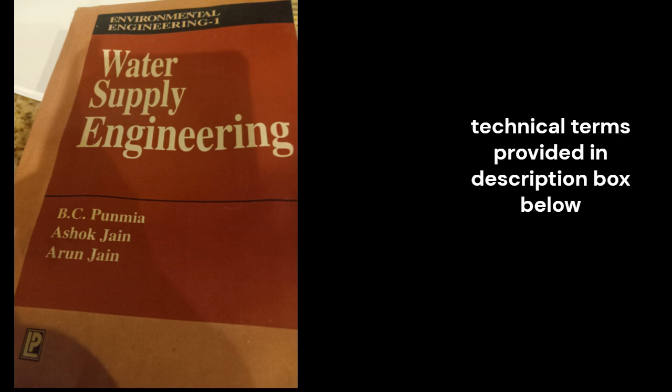And then next is about designing a flocculator. For designing a flocculator, there are 5 stages. The first step is to find all the design parameters, then computation of volume of flocculation tank, computation of power required, computation of velocity differential between the paddle and water, computation of paddle size.